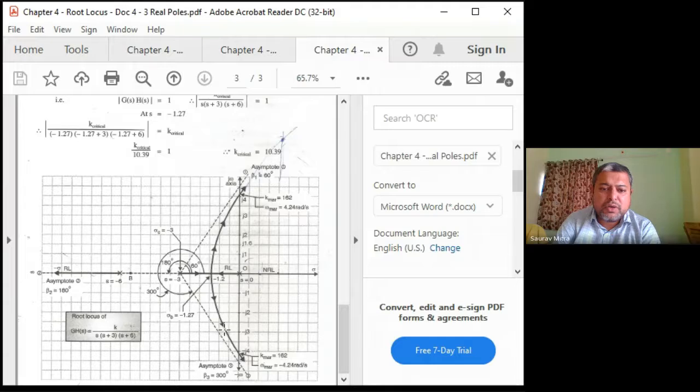And this root locus will touch this guideline. So this guideline is not the root locus. The root locus is this dark line. So this root locus will touch this guideline at s equal to infinity and at the infinity angle. Even if you don't want to draw these guidelines, it will do. But we should draw this because the root locus will be confined within this guideline. If this is the guideline, the root locus will stay inside it and will not cross outside. Okay, that is the significance.